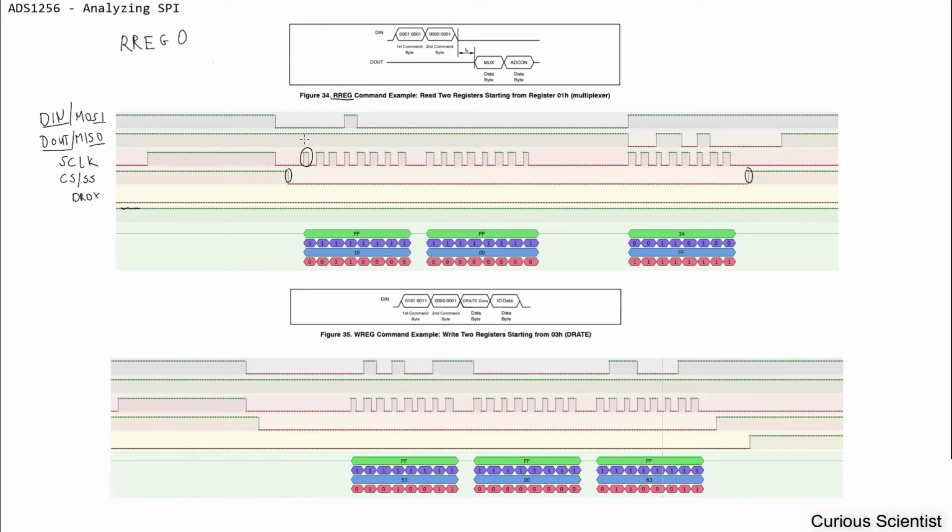SPI channels. What is the value, or level here? You can see that this is a high level, which means it is 1, and here we went down to low level and it's 0 when there is one clocking here. Now we don't read anything back from the ADS, because we are sending the command.